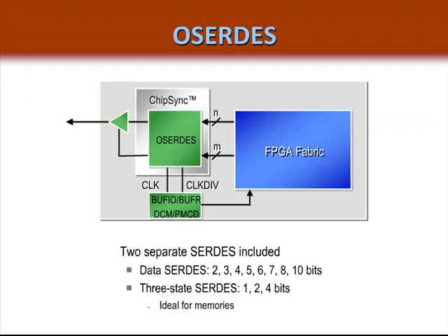Similarly, output SERDES configurations allow you to multiply by up to a 10-bit encode. A 3-state implementation is also supported because of the dedicated tri-state buffers associated with each I/O pin in the device. This makes the resource ideal for memory applications.